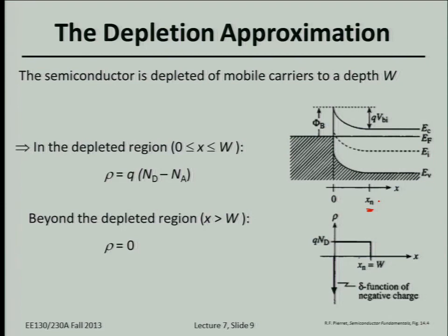So it's Q times ND. That's the density of coulombs, coulombs per centimeter cubed. That's the level of charge in the semiconductor. And let's assume that the electrons have pretty much all gone away, disappeared to the metal, down to a distance W away from the interface. Basically when the metal and semiconductor came into contact, electrons left, and so some thin, narrow width of the semiconductor is now completely depleted of electrons.